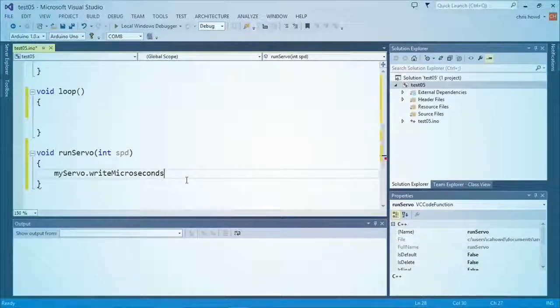Now, we're using a continuous rotation servo. If we put wheels on a regular servo, it would just go 90 degrees back and forth. It would not go very far. That's right. We did not pick that. So, for a continuous rotation servo, Paul, 1,500 is stopped. Instead of being in the middle of the movement range, it's stopped, and then if we go minus, it goes backwards. If we go positive, it goes forward, clockwise. Sounds like counterclockwise.